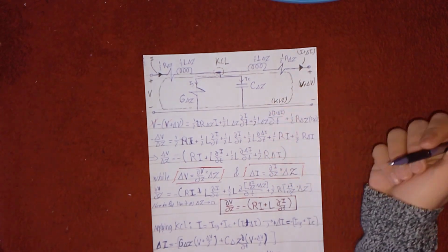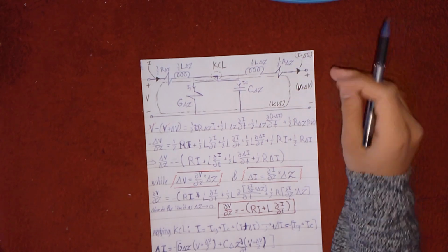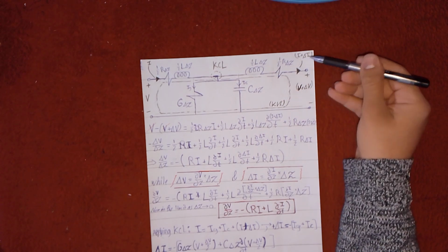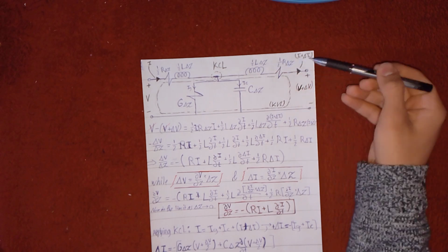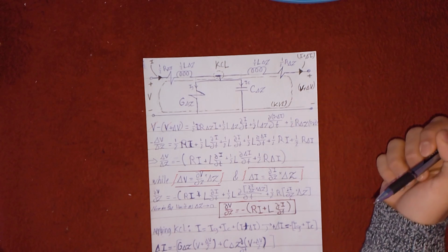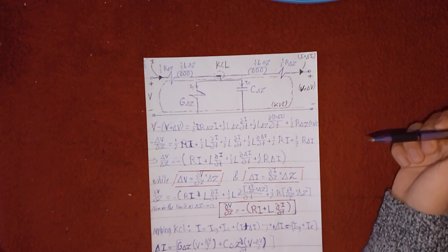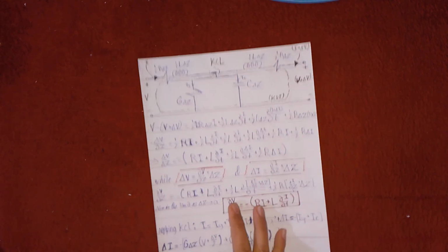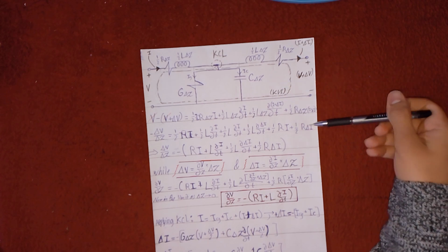So we take the partial derivative with respect to time. Plus here the same, but put in mind that the current becomes I plus delta I. So the half L delta Z times the partial derivative of I plus delta I with respect to time, plus half R delta Z times I plus delta I. Here these will cancel out, dividing all by Z and simplifying the equation, we get this.